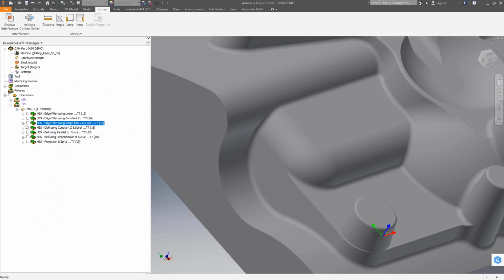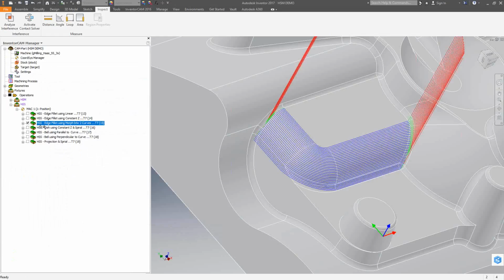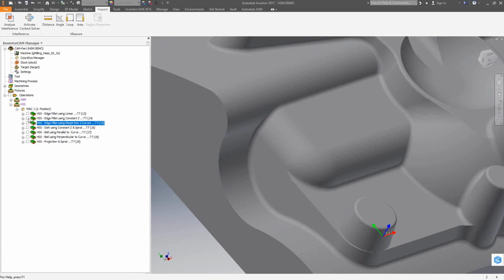If I calculate that and take a look at the toolpath, we'll see that it now blends the toolpath across the surface. So what we're actually getting is blending along the curves, blending along the surface. This will result in a better finish on this surface. Once again, on the edges there, I haven't changed the link between slices. I could have actually cleaned that up. But you'll see that between the three types of toolpath, this will be the cleanest one. There's no linkage issues or anything like that. Because we're morphing, blending with the surface, we get a nice smooth toolpath almost automatically.